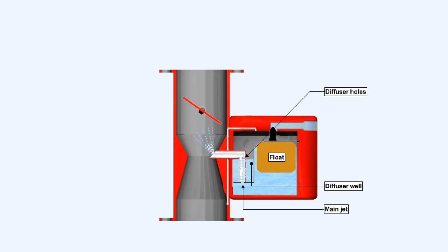The fuel discharge tube from the main jet passes through the diffuser well. A number of small holes are drilled through the wall of the fuel discharge tube at different levels. As engine speed is progressively increased above idling, the fuel level in the diffuser well drops, and progressively uncovers more air holes, which allow more air into the discharge tube, and by reducing the pressure differential, prevents enrichment of the air-fuel mixture. The process of drawing both air and fuel through the discharge tube also has the effect of vaporizing the fuel more readily, particularly at low engine speeds.